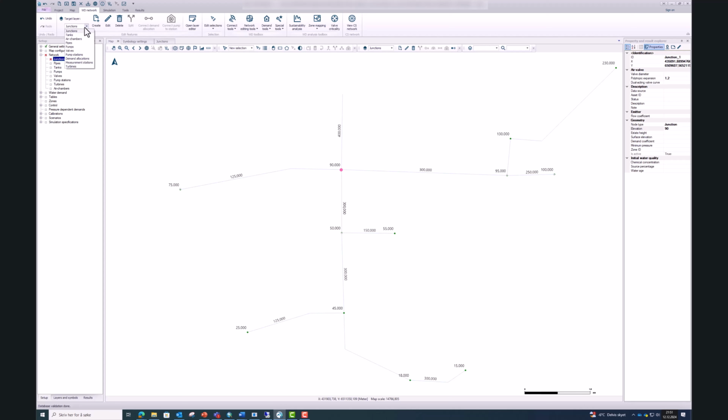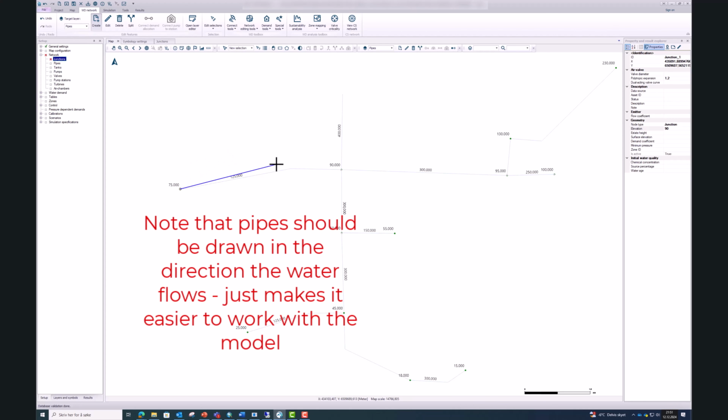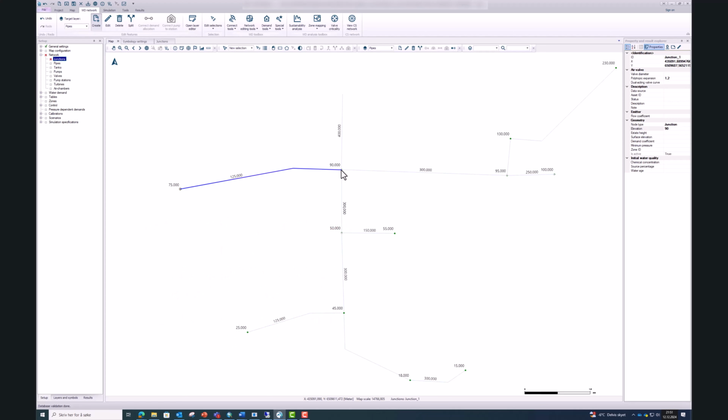Moving on, for the pipes, you just have to make this highlighted. We press on create, and when we hover over a manhole, you see that it becomes a bigger circle there, meaning that we are snapping to the manhole. So I'm clicking once, and I'm trying to follow the curvature here. And on the manhole I want to end on, I'm going to double click. Then my link is drawn.